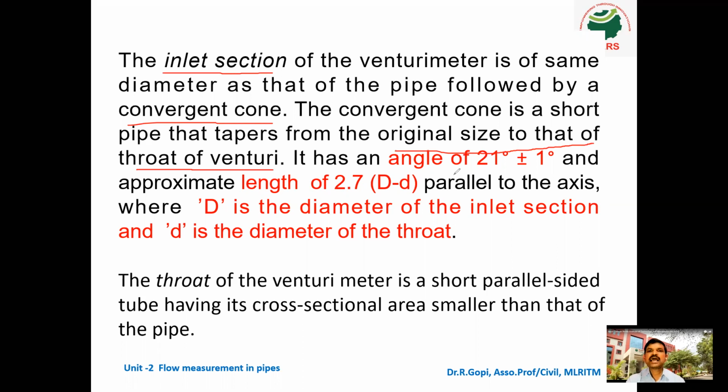It has a tapered angle of 21 degrees plus or minus 1 degree, and the approximate length is 2.7 D minus d, parallel to the axis, where capital D is the diameter of the inlet section.